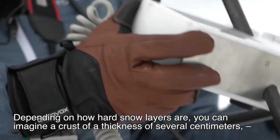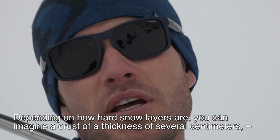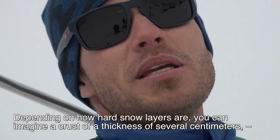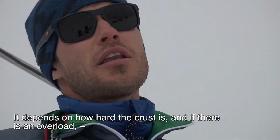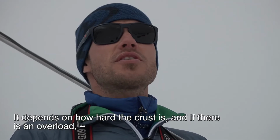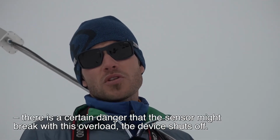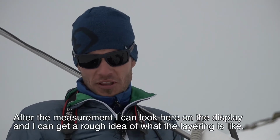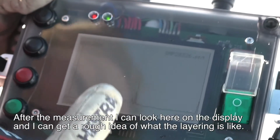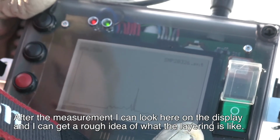Depending on how hard snow layers are, you can imagine the crust of a thickness of several centimeters, the device might shut off. It depends on how hard the crust is and if there is a so-called overload. And there is a certain danger that the sensor might break with this overload. The device shuts off. Now after the measurement, I can look here on the display and I can get a rough idea of what the layering is like.